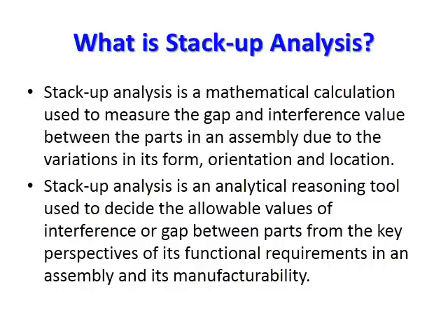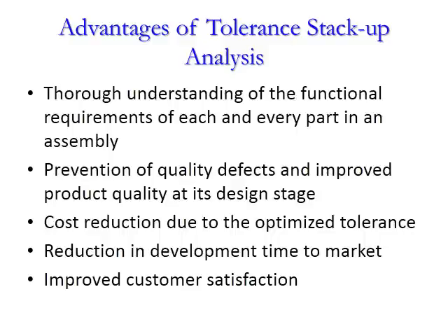What is stackup analysis? Stackup analysis is a mathematical calculation used to measure the gap and interference value between the parts in an assembly due to the variation in its form, orientation, and location. Stackup analysis is an analytical reasoning tool used to decide the allowable values of interference or gap between parts from the key perspectives of its functional requirements in an assembly and its manufacturability.